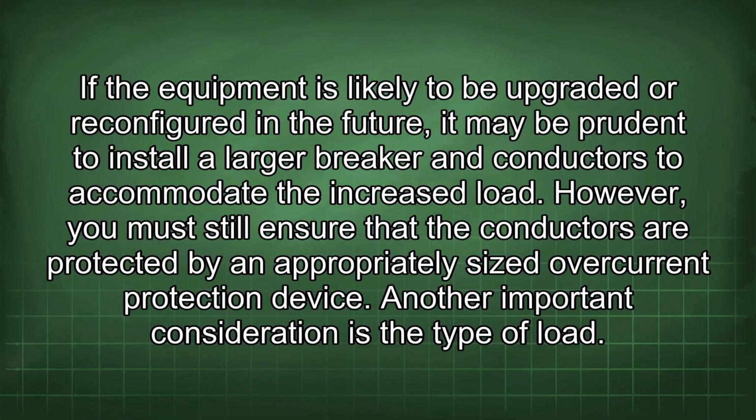If the equipment is likely to be upgraded or reconfigured in the future, it may be prudent to install a larger breaker and conductors to accommodate the increased load. However, you must still ensure that the conductors are protected by an appropriately sized overcurrent protection device.